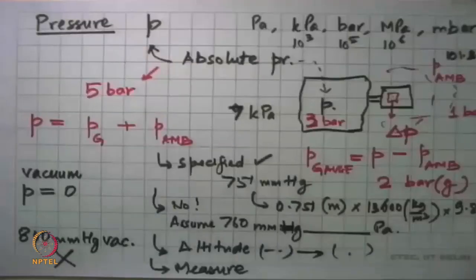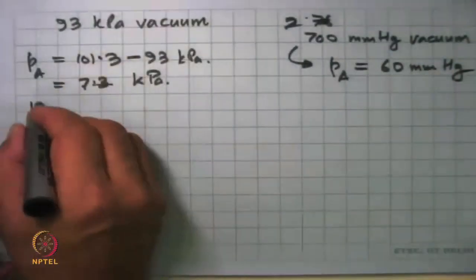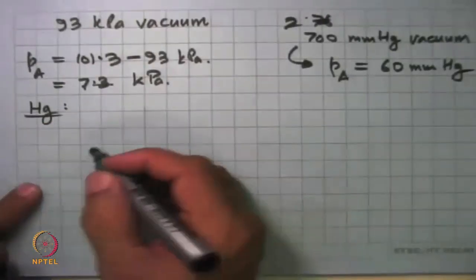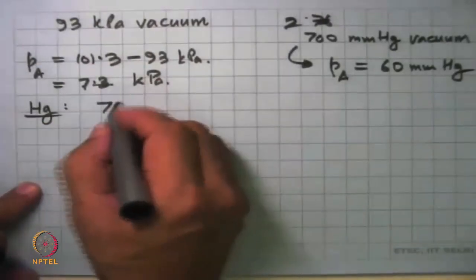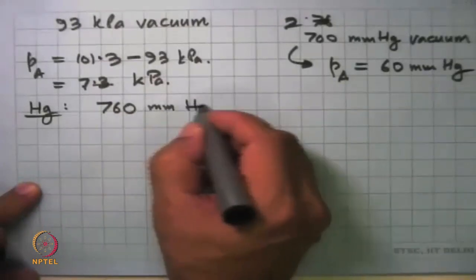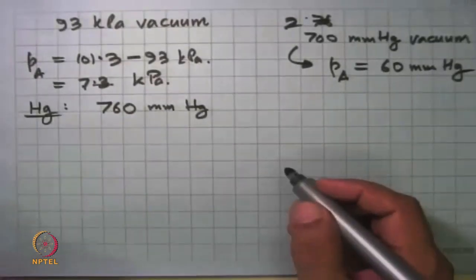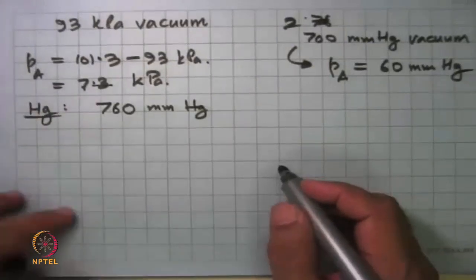Okay, the question here is, why do we measure pressure in terms of mercury? It is not necessary that we always measure pressure in mercury. We could use any fluid. Historically, mercury is the one that has been coming along. Water, absolutely fine, we could use water, but water has a couple of problems. Mercury is so convenient because ambient pressure is 760 mm, and so if you want to measure pressures below atmospheric pressure, a very simple thing works.